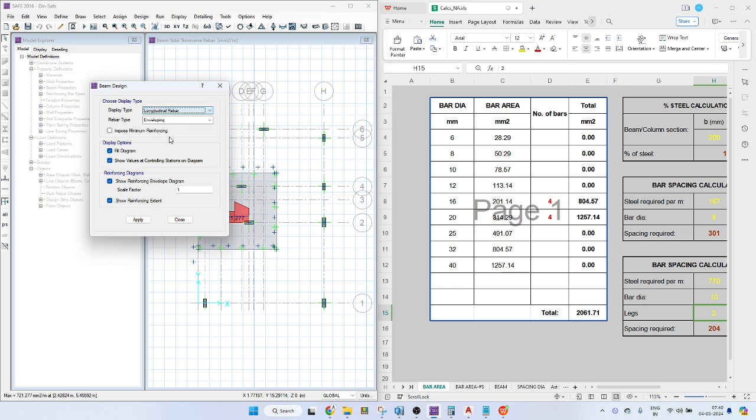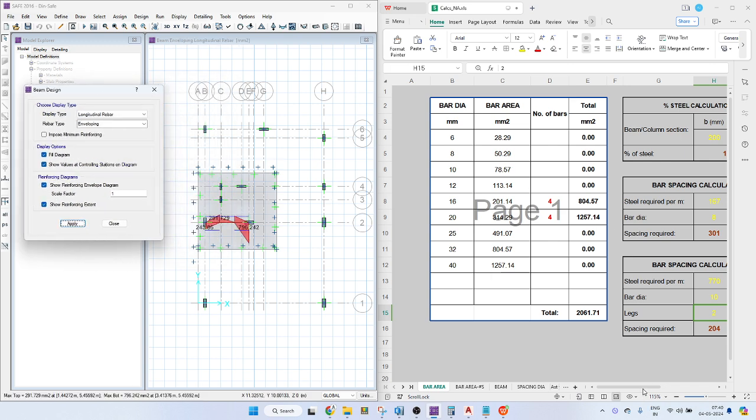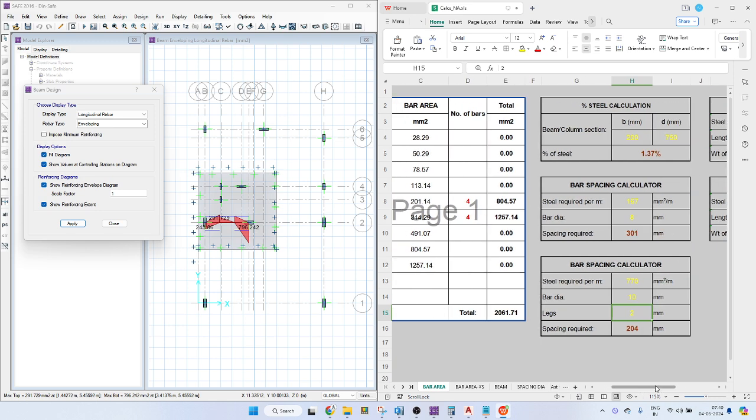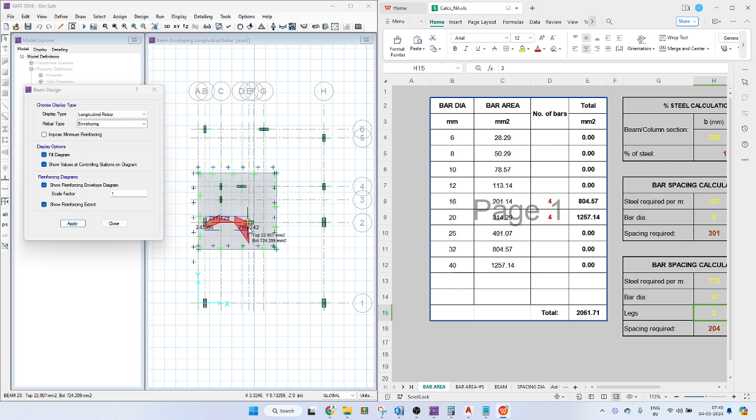Then what about longitudinal bar? How do you find that out? You need 796. Here top bar 291 we have to achieve. 291 can be achieved by 2T16. Entire length only it is telling.